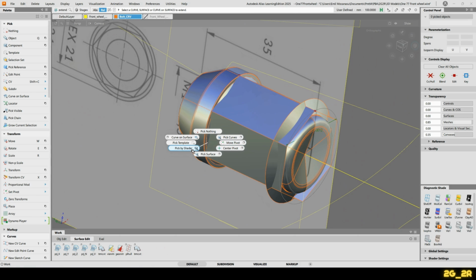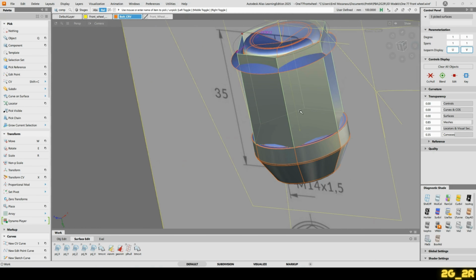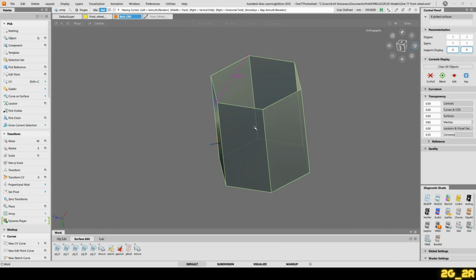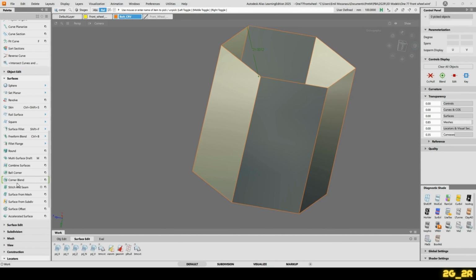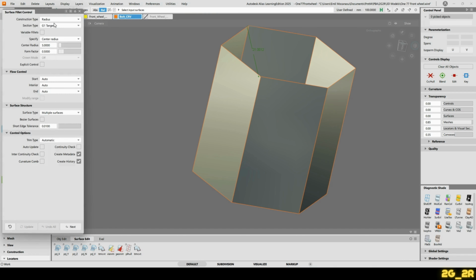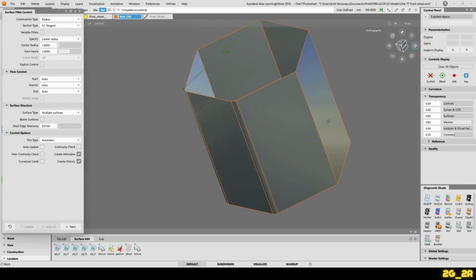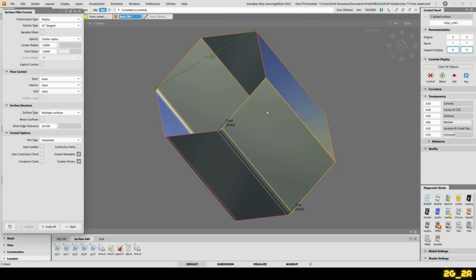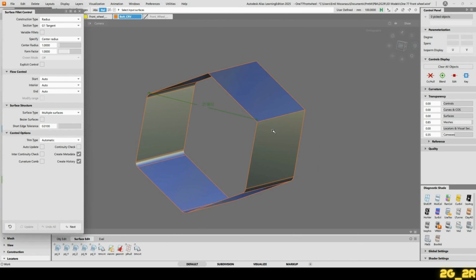So let's go ahead and take these surfaces and add those radii as they are important. We will do that by using the fillet tool to be found under surfaces, and then surface fillet, G1 tangent, let's say 1 mil, form factor 1. We will add those. Make sure your arrows are pointing in the direction where you want it.